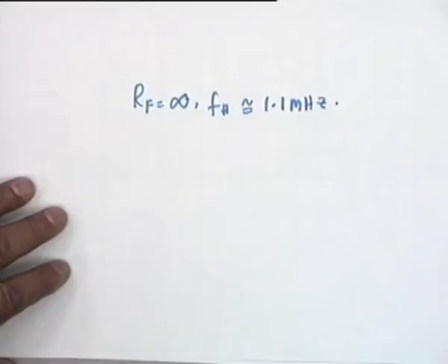Okay, right. So the approximation of Miller's, can it be used to evaluate the output time constant? No, cannot be used. Then how would we use it to evaluate the output time constant? Output time constant is okay. You see, we have to take help of Miller because we want to find the 3 dB points, the poles of the transfer function. Now, as far as the output is concerned, it does not see only RL, RF and C mu.